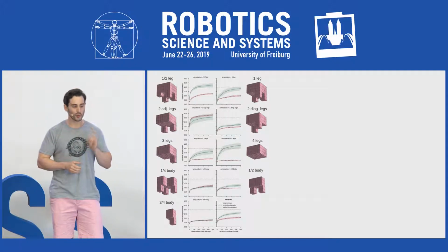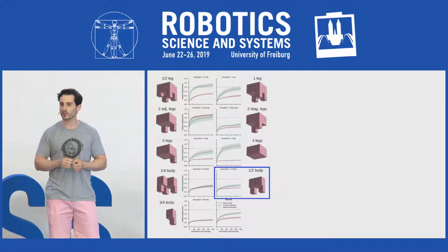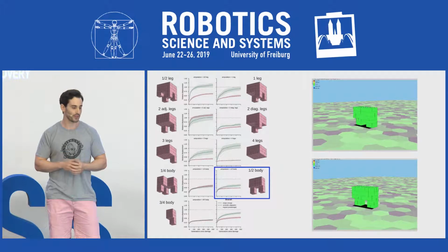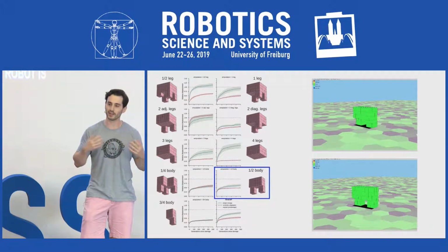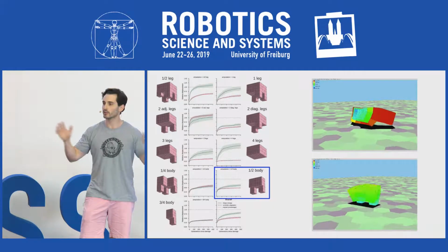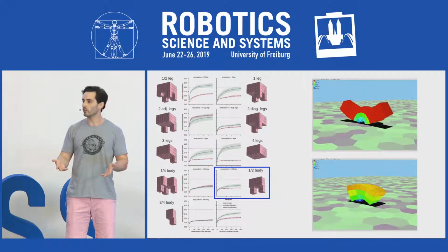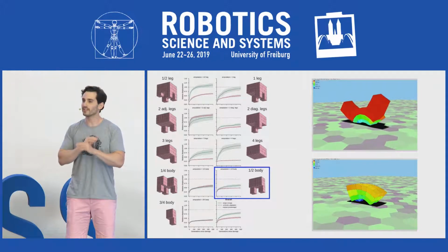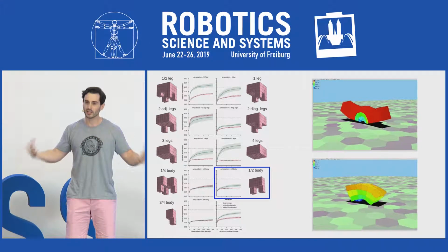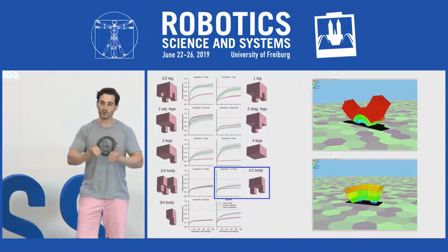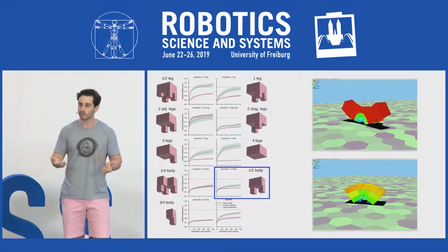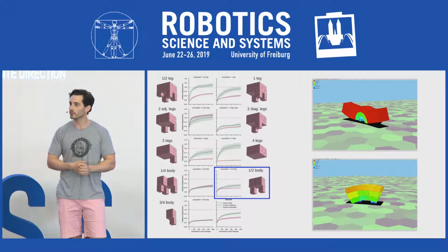And now I'll show two very different recovery strategies for the same damage scenario, when the robot's cut in half. On the top, the robot is about to greatly expand its remnant limbs, contract its spine, and flip over. On the bottom, the robot did the exact opposite in the same scenario. It contracted its limbs, expanded its spine for balance, and it moves in the opposite direction because of its shape change. But they both have the same controller.